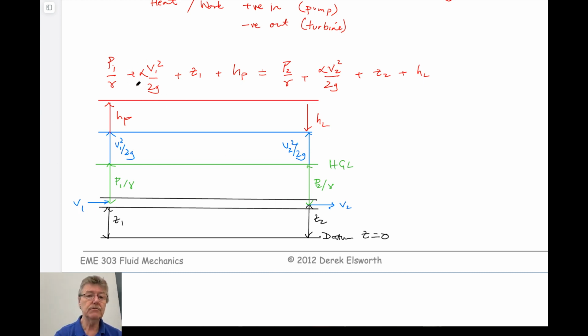So these represent the fact that the alpha values are, when we look at the Bernoulli equation, we look at the velocity across a pipe as just being a straight rectangular distribution of flow rates. In reality, if you look at the velocity across a pipe, because there are forces dragging on the side, the velocity profile is parabolic, as we'll find. 0 at the edges where it's kind of stuck to the pipe, as you'd expect.